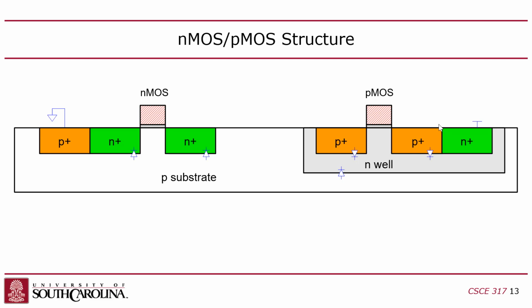So these are all built up from drawing polygons, rectangles mostly. We call them polygons, but they're really just rectangles on top of rectangles on top of rectangles. Every one of those rectangles represents a layer, starting from the bottommost layer, which is the well, and then there's metal layers on top of this that form the wires, right?